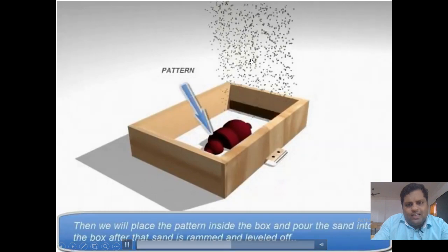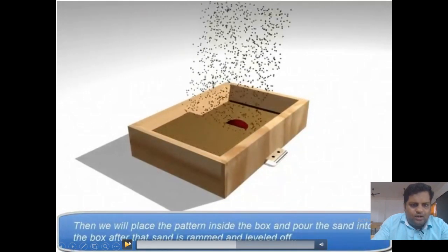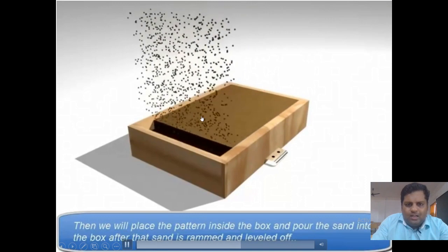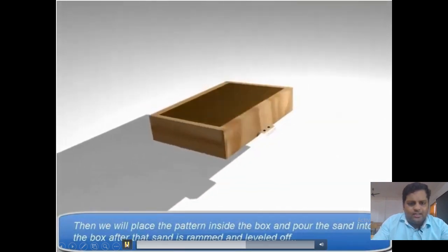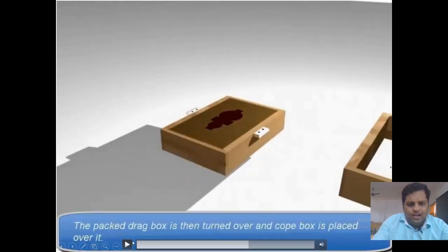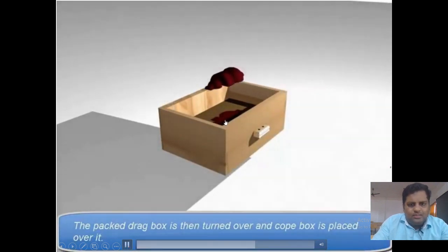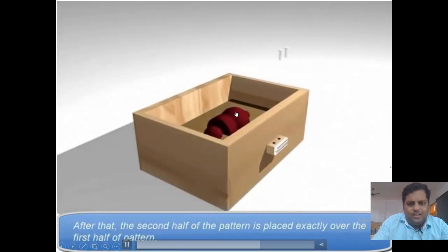After that, the sand is poured on the drag box. Then we need to do ramming. Using a rammer, we ram for a particular time period so that the sand gets tightened together. Then we reverse the drag box and put another box on it, which is called the cope. We put the second half of the pattern over here, and now the sand is poured.